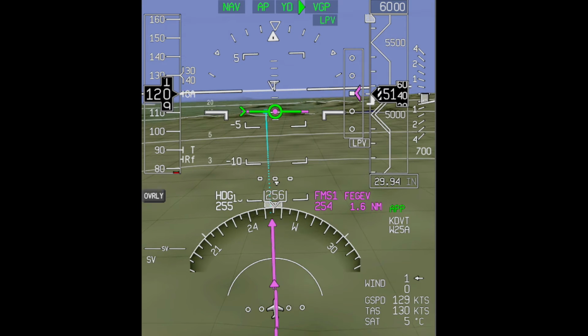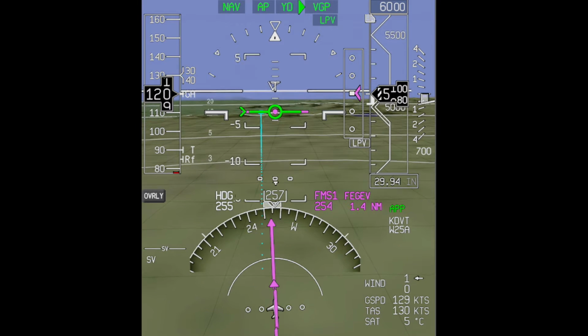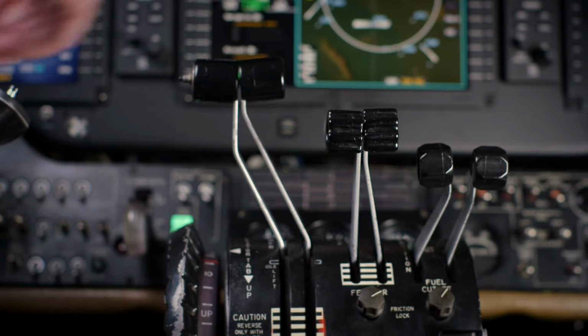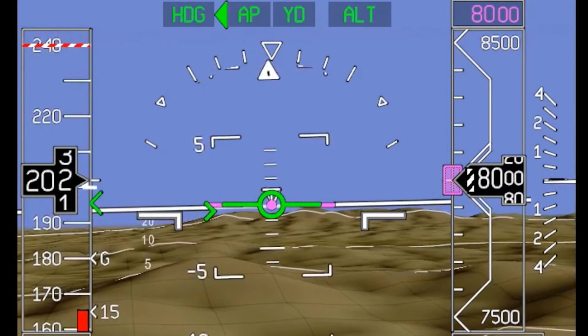The SmartView HUD symbology includes features such as a flight path symbol, track and heading reference symbols, and an acceleration chevron which aids in energy management. These features greatly improve situational awareness while reducing pilot workload.